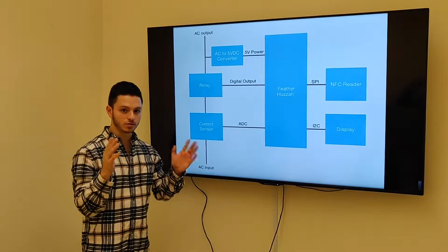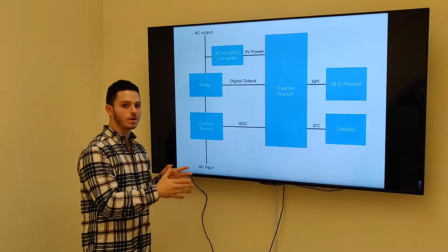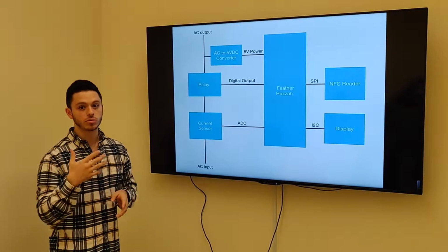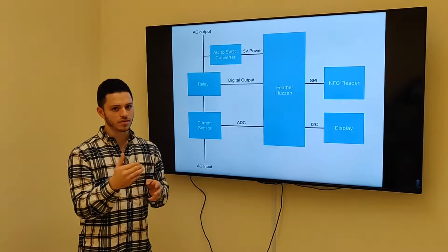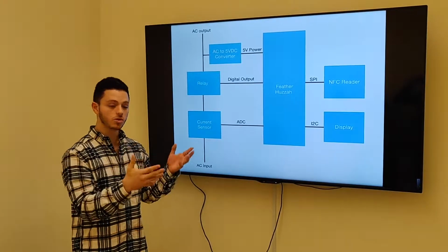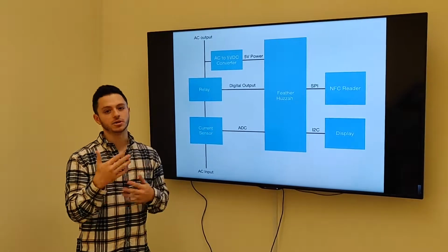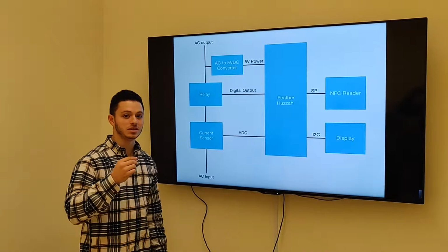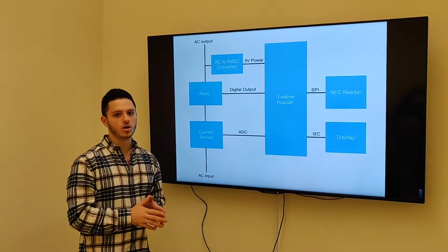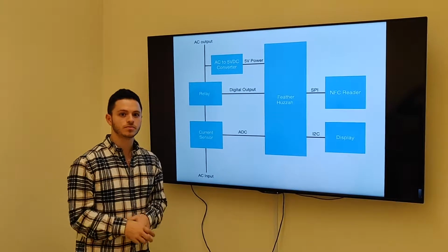We're then able to take the current from the voltage that we get. That's a linear transformation between the voltage and the current. We take that, which is a non-RMS current, we make it into an RMS current by multiplying it by 0.707, and then take that, multiply it by 110 volts of the wall, assuming we have a resistive load, and then are able to measure both the power and the energy, knowing the amount of time it took to actually take that measurement. Because the measurement is AC, it doesn't happen instantaneously, so we take a ton of samples over a period of about 100 milliseconds and grab the max value from there.